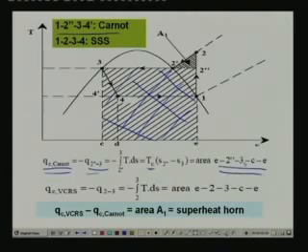Now what is the heat rejection in the standard vapor compression refrigeration cycle? That is nothing but heat rejected during process 2 to 3, that is nothing but the area under curve 2 to 3. Okay, that means this area plus this area. Okay, so this is equal to area E2 3 CE, right, the entire area.